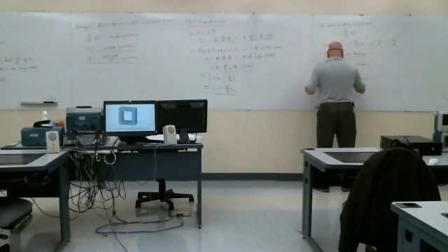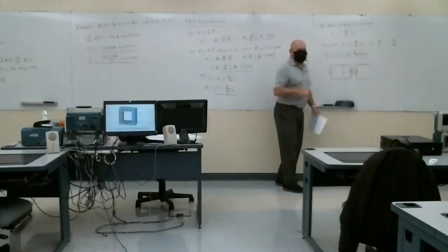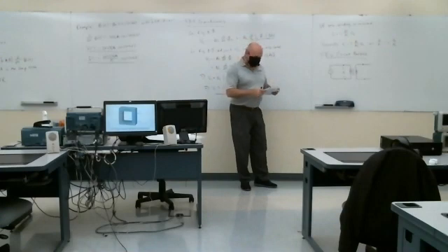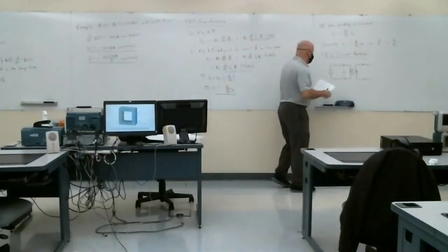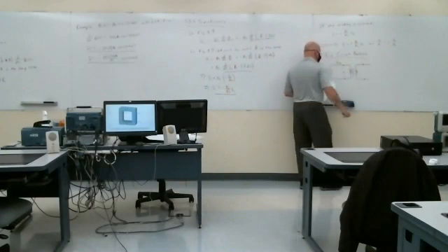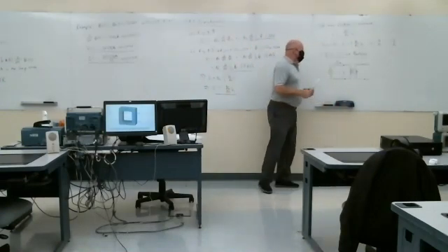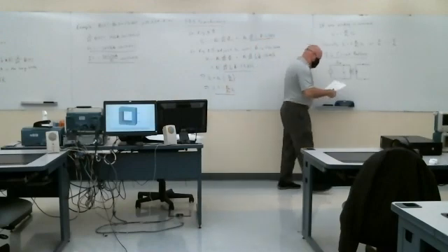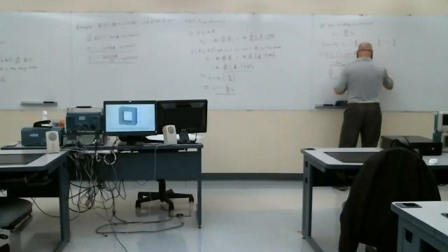The primary side of the transformer is the side that has the source attached to it. The secondary side is the side that has the load. This is the convention he uses in this textbook, the same as was used in circuits. V1 is the voltage across the primary. I1 is the current entering the primary. On the secondary, we have a load called ZL.